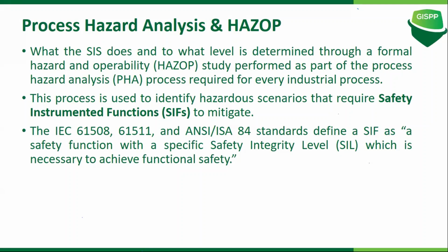If we don't know the parameters, we cannot control them. And as in cybersecurity, we need to evaluate these factors as well, and ensure the integrity and the availability of these devices. Like I said, the CIA triad is also applicable to the SIS. So we do this study, called HAZOP, Hazard and Operability Study. The process is called PHA, Process Hazard Analysis, and it provides a set of controls, the values that should be configured in the SIS.